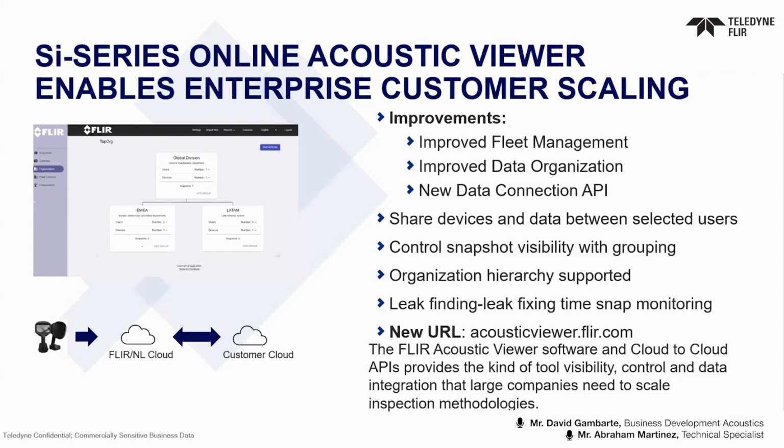So you could establish, for example, in a factory that we are doing inspections on a weekly basis, and all those leaks found need to be fixed within, for example, 2 or 3 days. And then you can follow up how much time is taken to fix those leaks in every one of the production plants or production units.